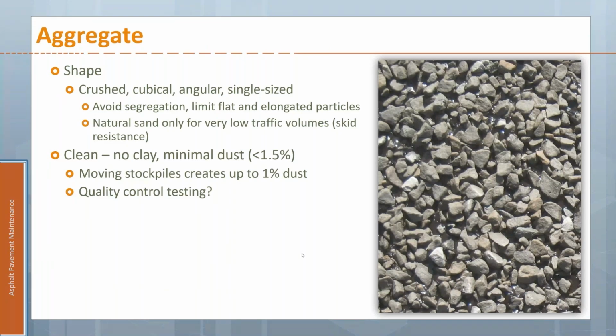Same thing with stepping on fresh gum with dirty shoes. If you have nice, new, clean shoes, you step on the gum, it's all gummed up in there. But if you have old, dirty shoes, it doesn't affect you so much because it doesn't really stick. Same thing's happening here. If we have dirty, dusty aggregates, it's not going to stick to the binder that we're putting down. So when you see major problems with chip seals, I would say 90% of the time it goes back to an aggregate source that has too much dust. And that dust is a barrier.